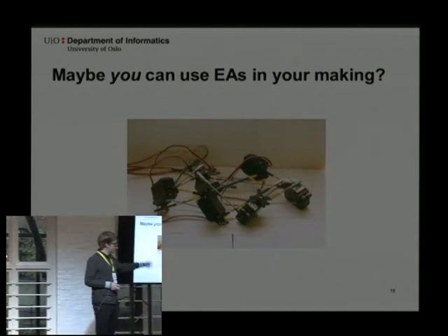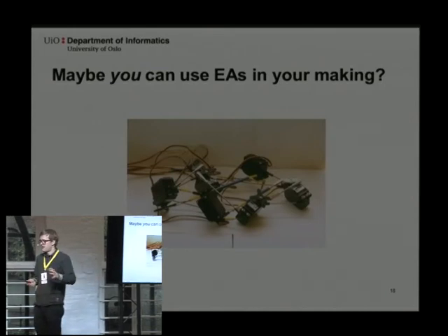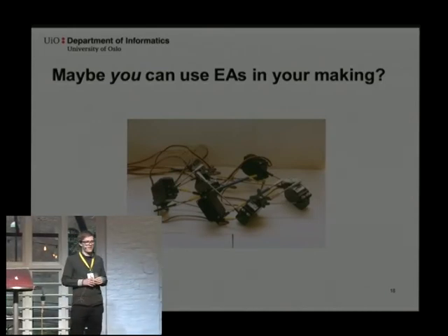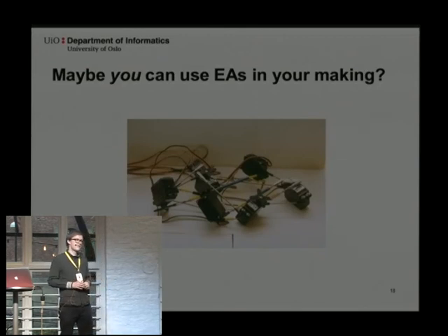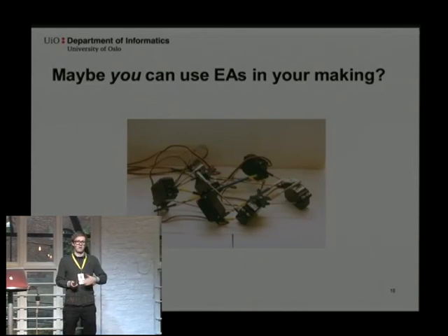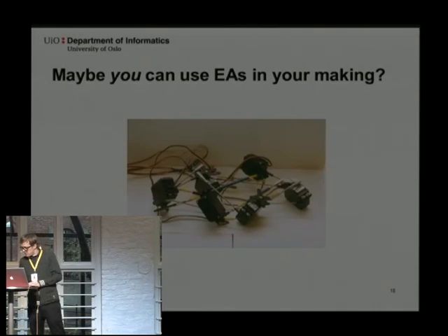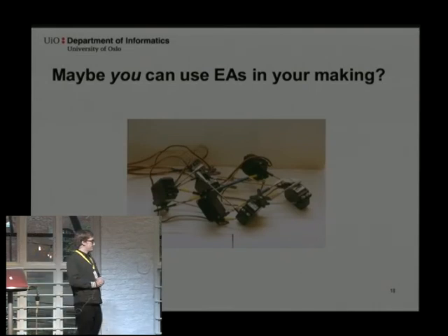There were actually some researchers doing something similar a while back. They built a random servo and stick robot, applied a genetic algorithm, and made it walk. One easy way to start is to put an LED on your robot, and then have a camera or a Wiimote in the roof, and use that to easily track how far the robot has moved, so you can do it at lower cost than a motion capture system. So that was my content, so thank you.